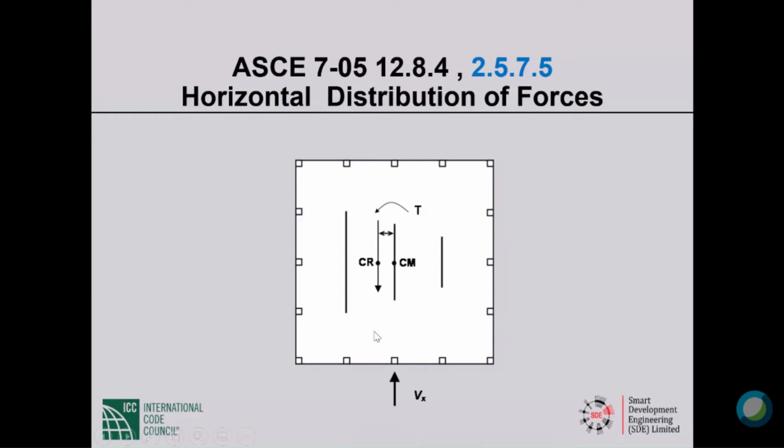Okay. Now, the story shear acts through the center of mass, which is pretty much at the geometric centroid of the plan, because mass is, I keep on saying, mainly in the floors and the roof, not so much in the vertical elements like the columns and the shear walls. Okay, so the fact that this shear wall is longer than that shear wall does not move the center of mass from the centroid of the section.